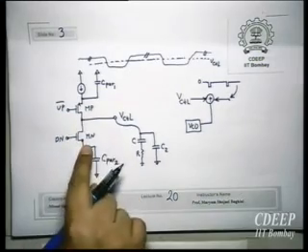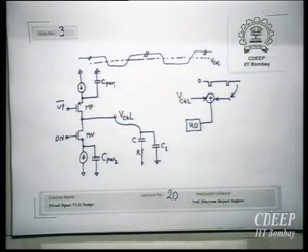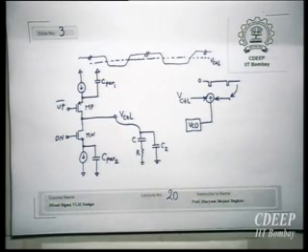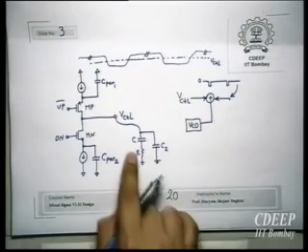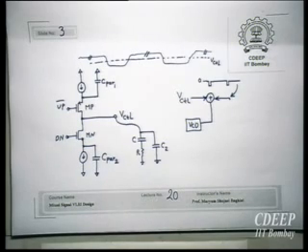Now at that time, this node and VCTL will get connected. And then these three voltages are different. So what happens? Then there will be a charge sharing, which will create a new value of VCTL. So this will be a problem. Of course, if the values of C1 and C2 compared with C par 1 and C par 2 are quite large, then this will be negligible. Otherwise, you will have a change in the value of VCTL just at the start of switching during those narrow pulses. So this is the charge sharing effect.